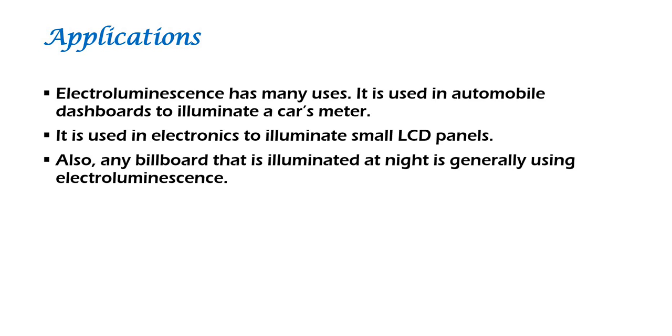The first thing to understand is how a circuit sees a piece of electroluminescent material. It sees it as a capacitor. The resistance between the two electrodes is almost infinite and thus DC will not pass through it. But when an alternating voltage is applied, the buildup of charge on the two surfaces effectively produces an increasing field, called an electric field, and this causes the phosphor within the field to emit light.